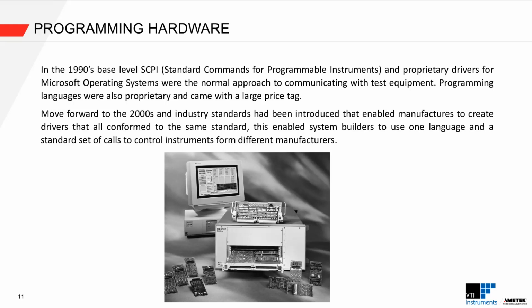And if we pull this all together in one slide, then we look at the actual task of programming your test system. In the 1990s, it was a case of using either SCPI, which was standard commands for programmable instruments, which was a form of driverless control, or failing that, there was always the option to get proprietary drivers.